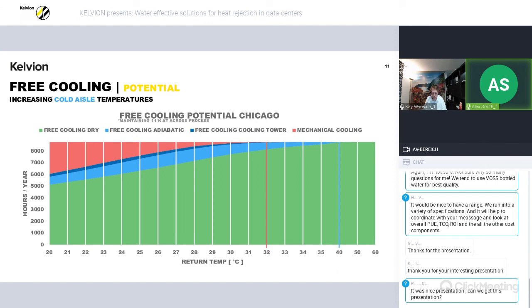You don't need cooling towers, you don't need water. The lower that temperature profile becomes, the more susceptible you are to needing mechanical cooling and water, because your temperature profile gets closer and closer to the ambient and starts to limit your LMTD, your approach. If it sinks below ambient, you have to have some form of additional cooling to condition the air or to assist in the cooling of your process.